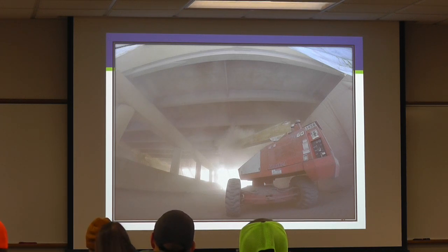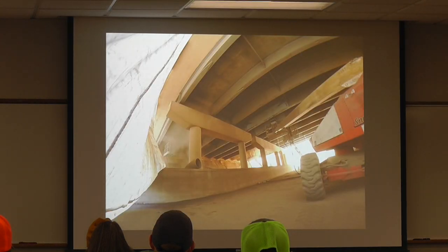If you show up on the job and they're just getting fired up, starting to blast, step out. You don't want to be standing inside. Maybe some of you have been around some sandblasting before, I'm not sure, but they could be running 4 lines at, I think, roughly 150 pounds of line pressure. It will peel the hide right off of you if you get a direct shot from it. So when this starts, just excuse yourself until they're done.